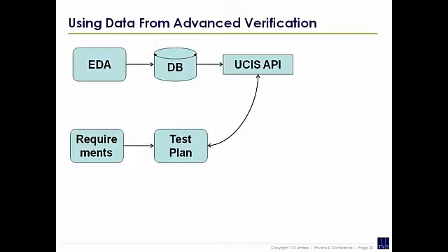So this is a very, very high-level view of what we're doing. There's our EDA tool. That could be the Xilinx tool. This is the simulator, effectively. So it's either the Xilinx tool, it could be a Mentor tool. I know some people use Mentor, maybe Cadence, maybe Synopsys. When that runs, it generates a database of coverage information about what it did during that simulation. So for each simulation, you get a small database telling you what that simulation did.